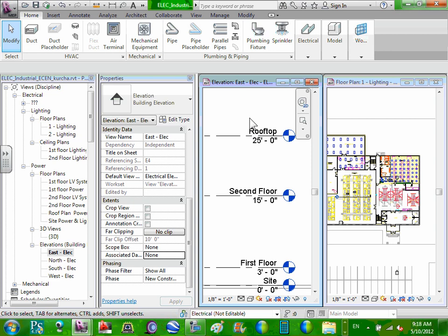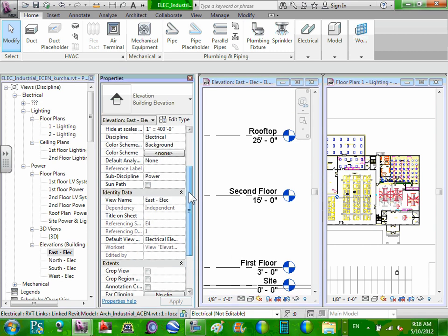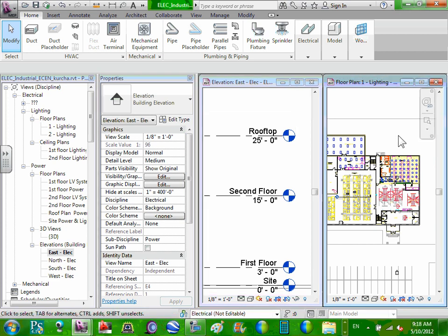So a lot of times when we have it set up like that, we'll have bleed through the roof. We'll have roof elements like a rooftop unit or a PRV bleeding through onto that first level when we don't want it bleeding through on that first level. So a lot of times how we set up our level, and there could be a reason for it, I'm not as familiar with the project, and it's not unheard of.